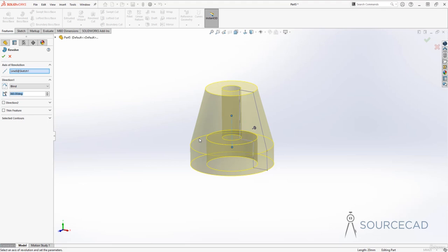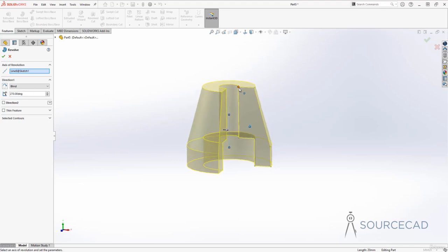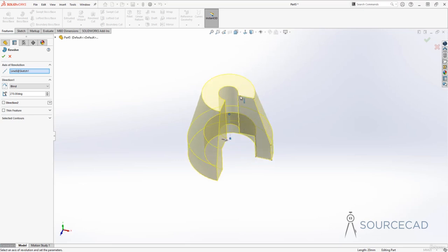Now in order to see what we have here, I will first change this parameter, which is the complete angle. It is 360 degrees. Let's make it 270 and press the tab key. Now in this case, this sketch has started revolving. So this is the sketch we started with, and it has started revolving about this line. So now once it started revolving and it revolved to about 270 degrees, we got this. So that's what this revolve feature is.